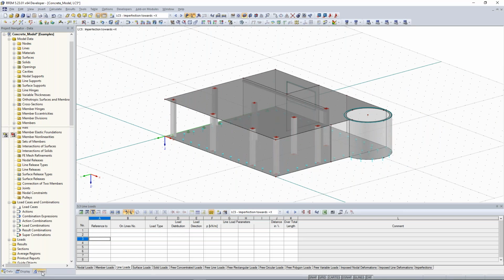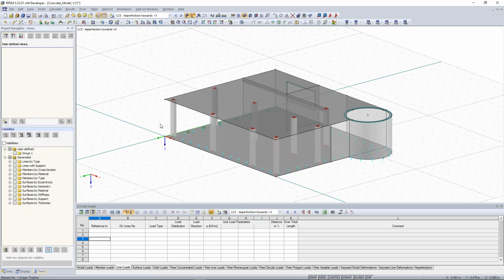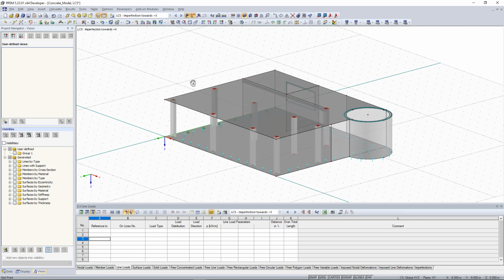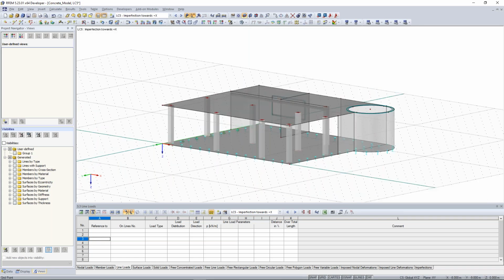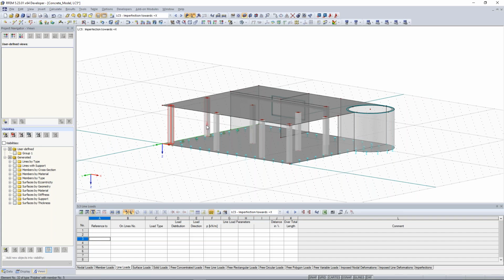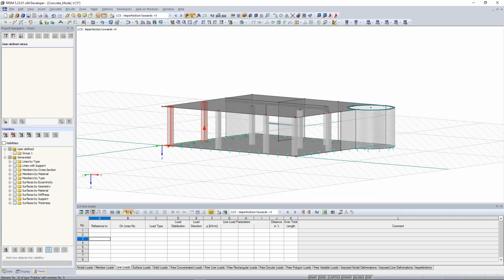Click here to the Views navigator, and now you just want to see all columns. Yeah, you can select every column, and then you can say, okay, show me the visibility, show me these objects, show me the visibility by selected objects.